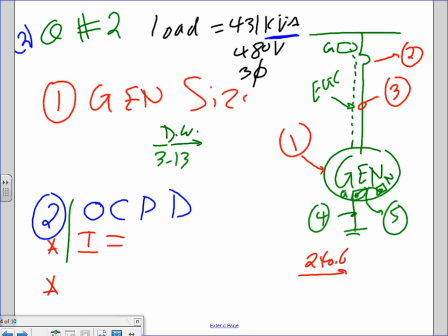So did you guys hear me tomorrow, Derek? You're going to have one of them in kW. So what do you need to do? You take the kW, this number, and divide it by 0.8. That will give you the kVA. Then you continue with these steps.